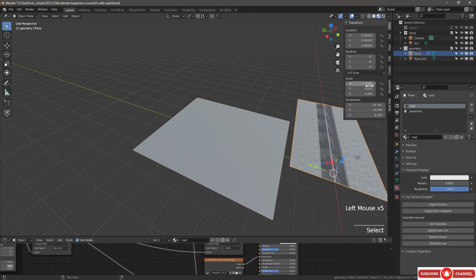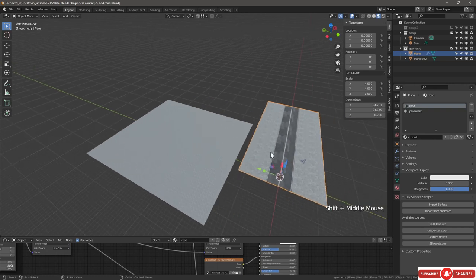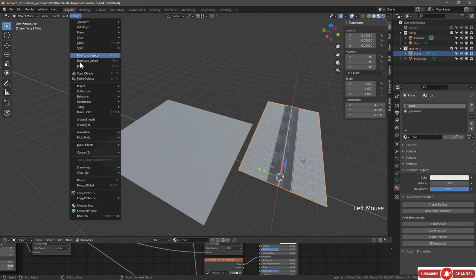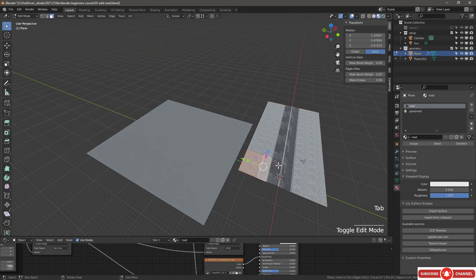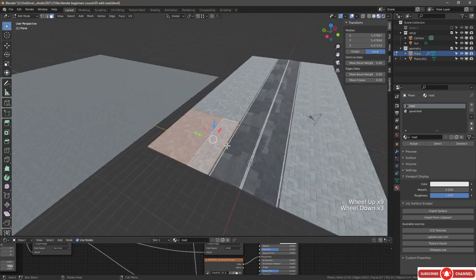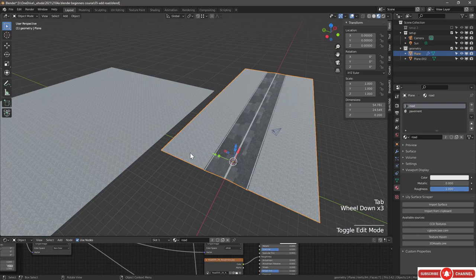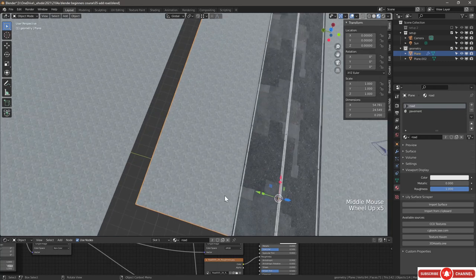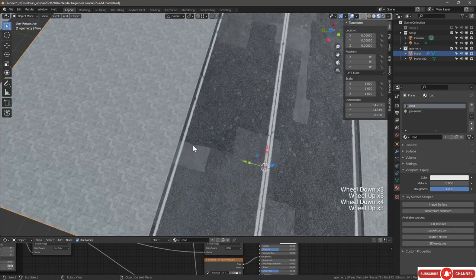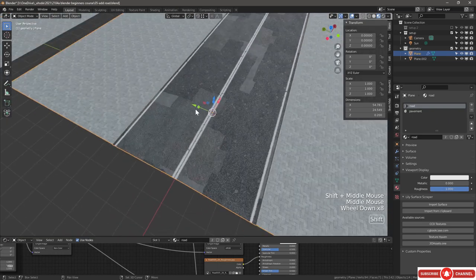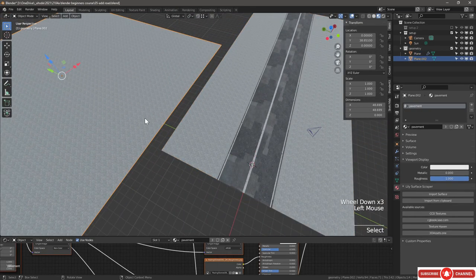And I think the reason is that our object scale here wasn't applied. So it's that scale times 4. So what we need to do is apply our scale here as well in our road. So object, apply, scale. Now if we go into edit mode again, everything should still be selected. UV, UVW, box. So the nice thing here is that no matter our object size, when we do the UVW box command, it unwraps everything to almost the real scale in a way, which doesn't exist in any of the other UV tools, at least not to my knowledge. So I find this very useful command. This pattern may look a little bit tiled initially, and don't worry, we'll fix that later. Right now, we're just putting these as sort of placeholders.